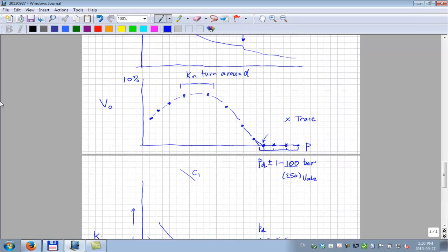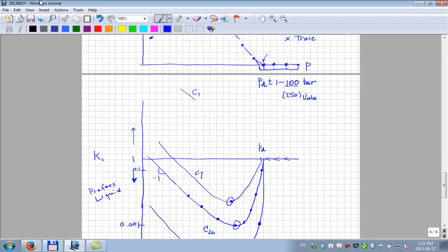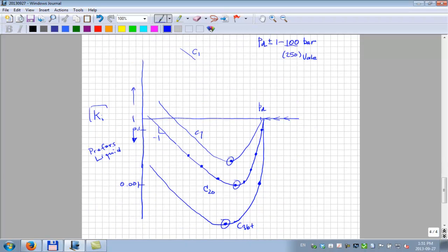So that was just a general comment, but it does feed back on what we've learned earlier. Remember the K value. If you remember nothing else about K values, and I'm sure many of you can't wait to get out of this flash calculation mode, if you remember nothing other than that if it's bigger than 1, that component has a preference to be at home in the gas, and if it's less than 1, it has a preference to be in the liquid phase. That I want you to carry with you, all of you.